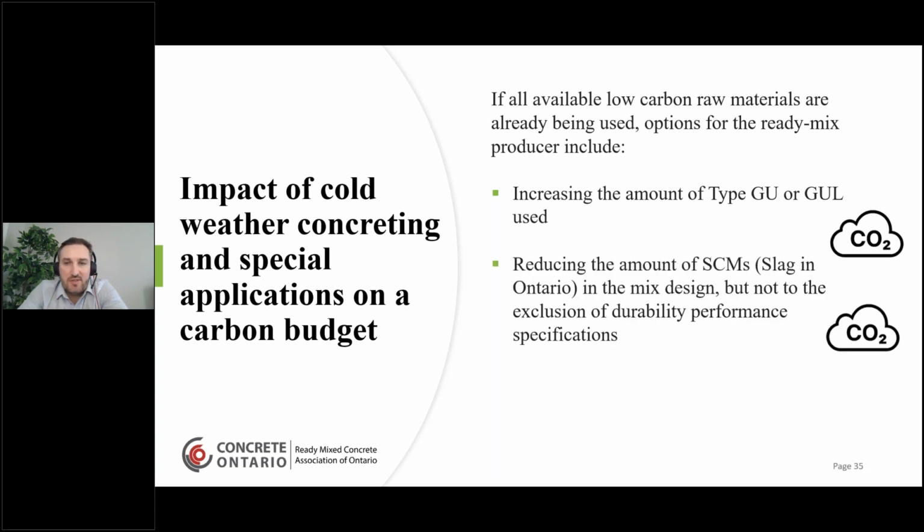You also may have to reduce the amount of SCMs you're using, so slag primarily in Ontario, to get you that better performance, to get that concrete to set up quicker. You may have to reduce the amount of slag you're using, which again increases your CO2 output of that mix design. So there's definitely challenges in setting a carbon budget, and you can incorporate the use of specialty admixtures again to help you there as well.